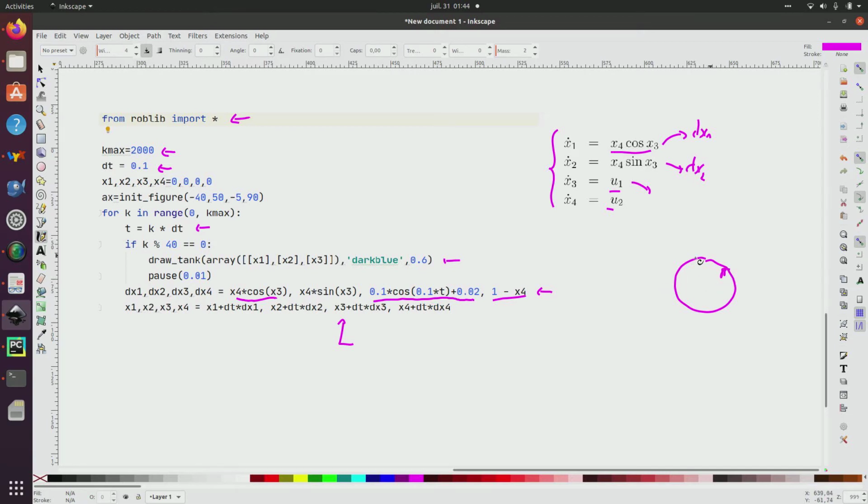This is for a complex reason of topology, but when I deal with three angles, like phi, theta, psi, which are Euler angles, then we may have some singularities in the representation due to the shape of the manifold, some kind of surface, which has poles.